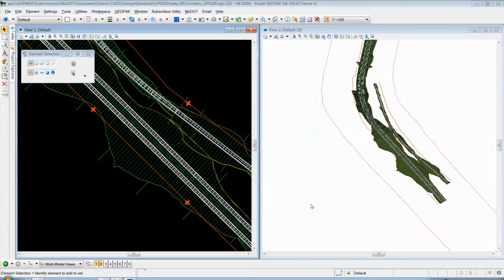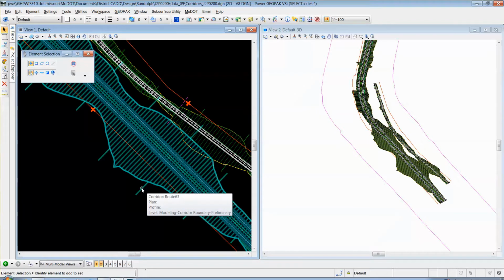This video is for the individual exercise for the Route 63 earthwork in Chapter 10. Okay, right now I have the corridors file open, and if you go through step 1, that's what it asks you to open: the corridors file. The main reason we open the corridors file is because we have to change the template drops before creating our cross sections for our earthwork.